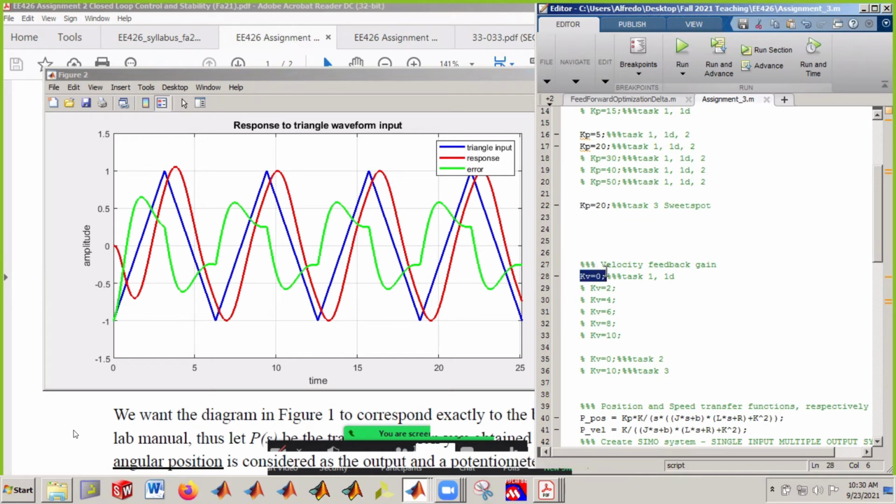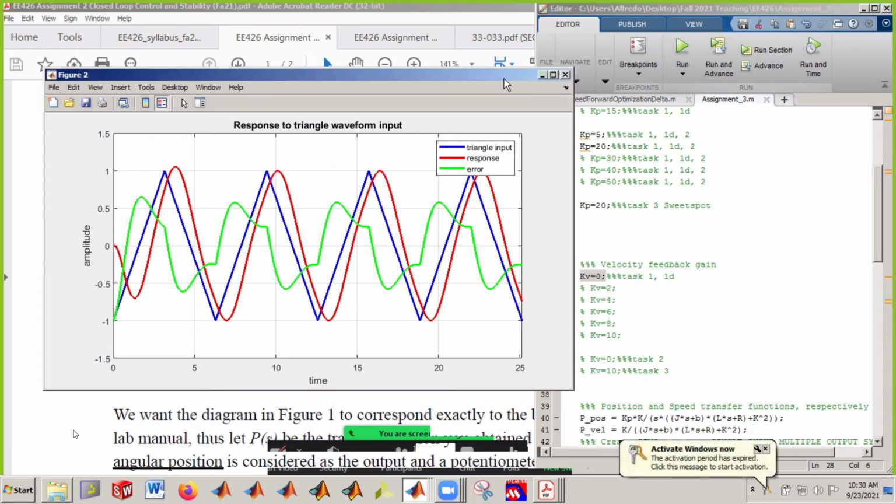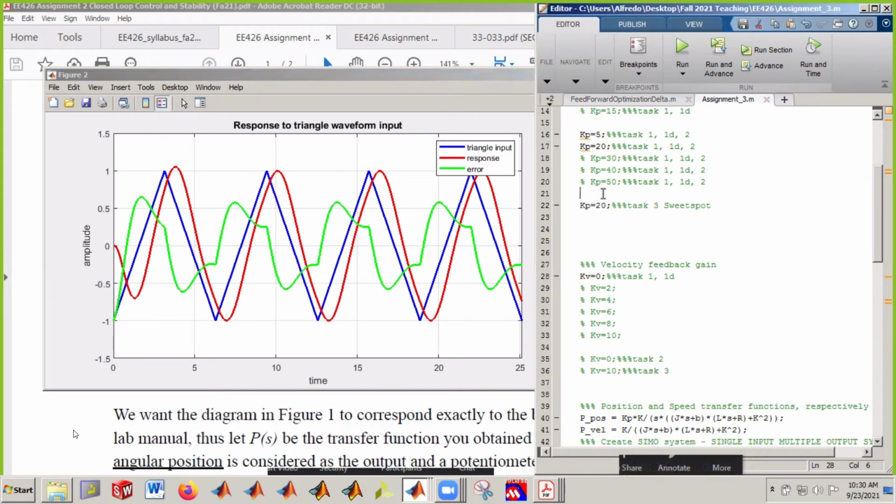Now, when you do this, as I was saying, you need to worry about the stability of this thing, because you guys may not know this, but when you introduce time into the equation, a lot of things can change and a lot of things become more prominent. So we really need to worry about the stability of these things. That is why we spend so much time on a PID, because it is so easy to understand, and we understand the stability issues behind a PID, which are just linear systems.